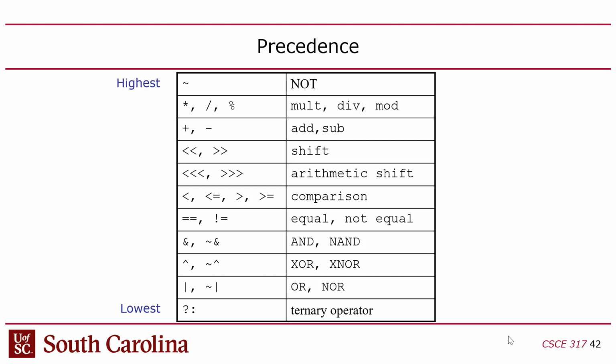You might say, wait a second, I can write a divide in my C code and compile it for the Nios. Yes, but it doesn't get mapped to an instruction. It gets mapped to a function. It calls a function and does a divide in software using shift and subtract instructions. I don't think the Nios has a divide. I could be wrong about that, but I don't believe it has one. The ARM v7 architecture, which is the one just previous to the one that everyone's got now, didn't have a divide.